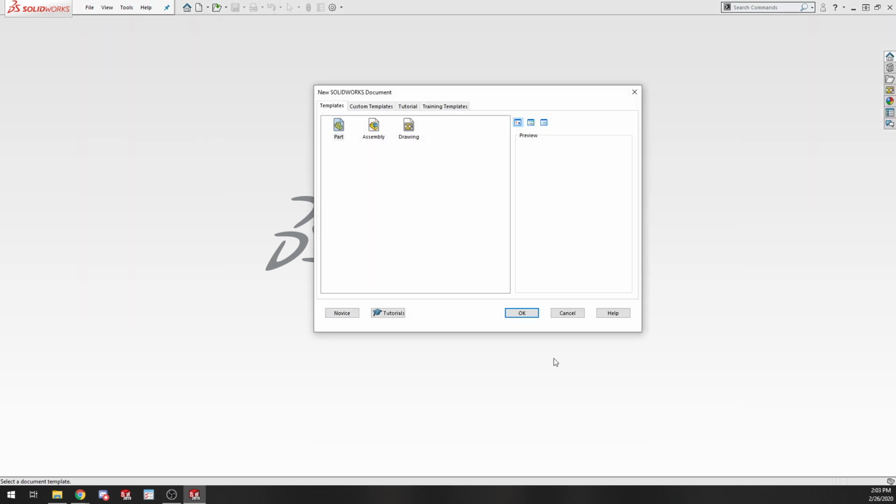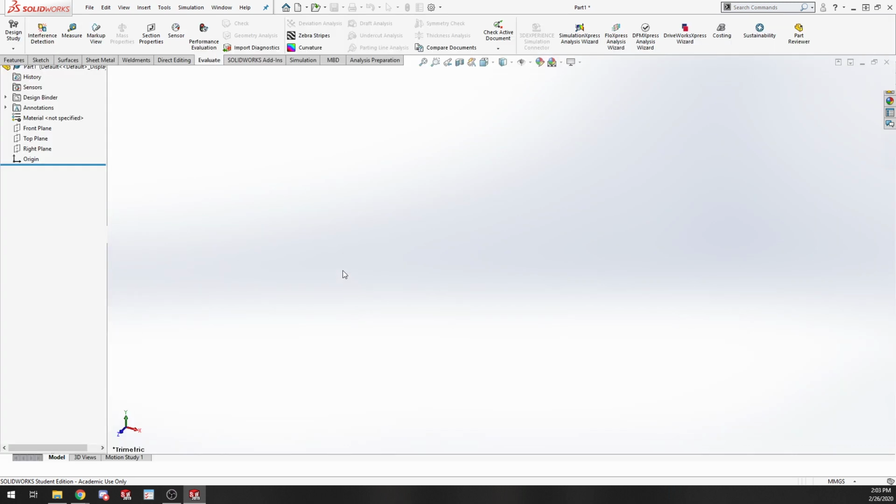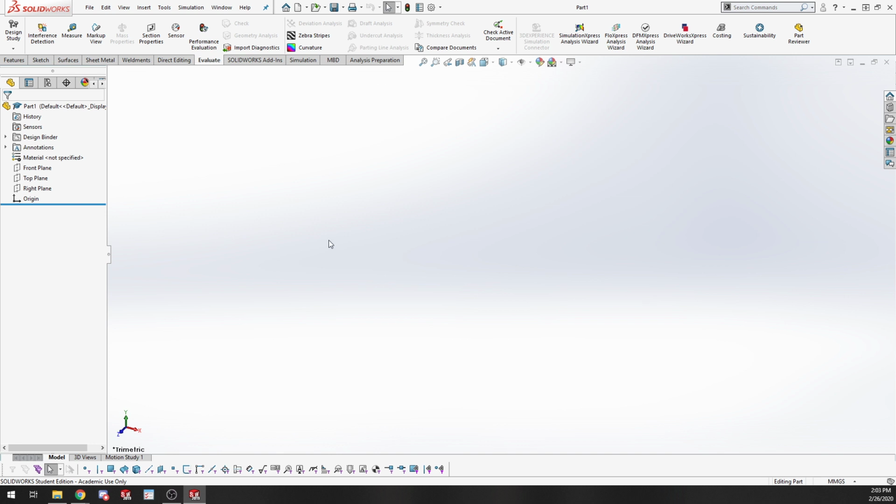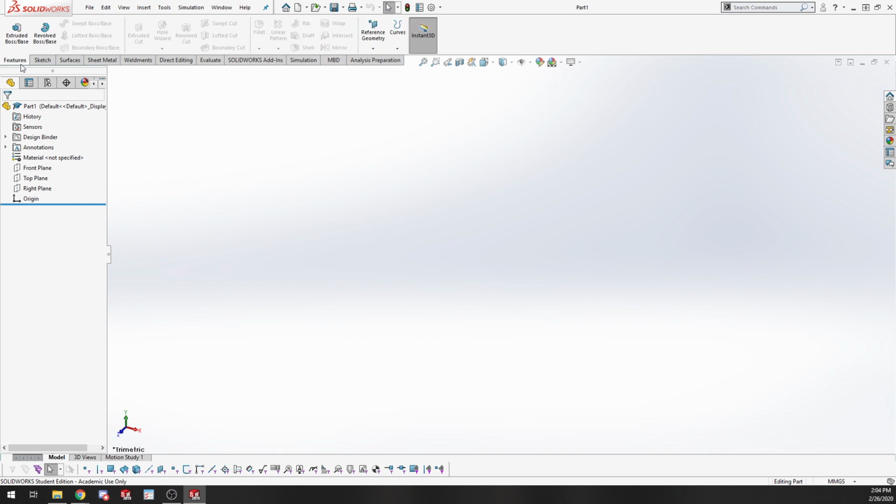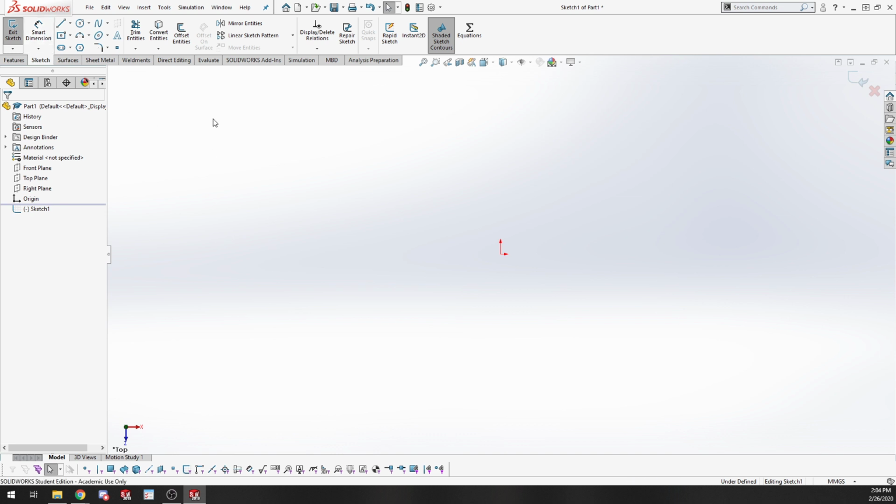Cool, new part. So working with surfaces, the big thing that I want to stress is that very rarely are you ever going to create a part entirely with surfacing. There's almost nothing that you could ever conceive of that needs to be designed solely with surfaces. Usually you're going to start with a solid body that defines your simple parts. If we're starting with a cylindrical shape, we'll just make that cylinder first and then add in the extra stuff. So we're not always going to be doing everything with surfaces. To keep things simple, we're just going to design the grips on our steering wheel here.